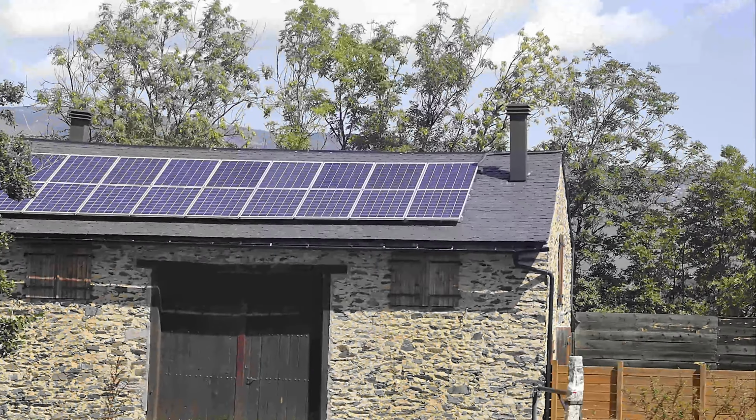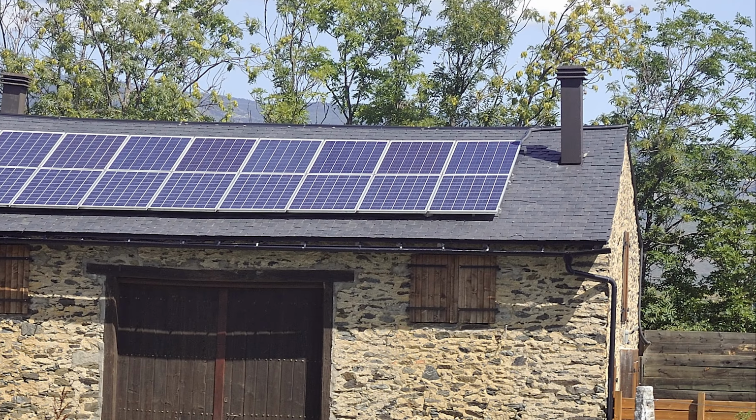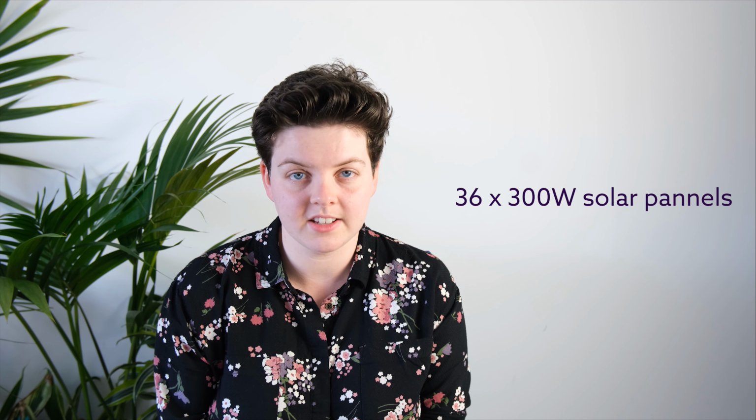A small installation is one which can generate no more than 16 amps per phase. So if you've got a 3-phase power supply and you want solar panels on your building, you'll be limited to around 11 kilowatts of generation, or to put that in other terms, about 36 solar panels.